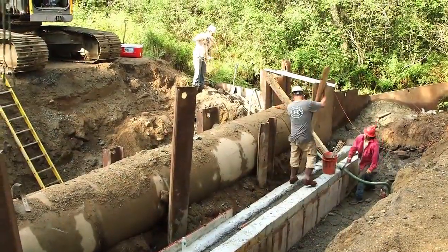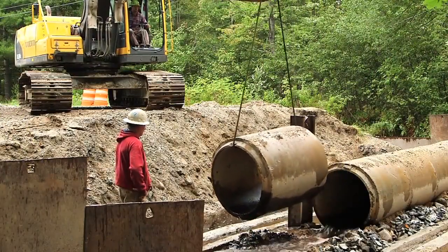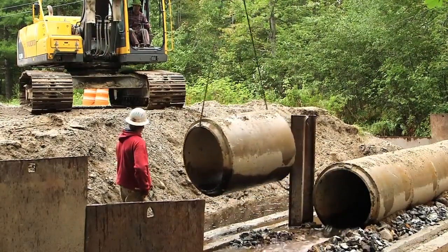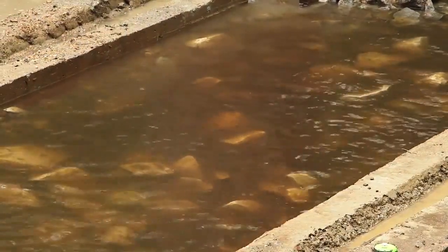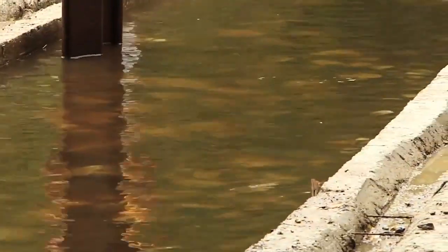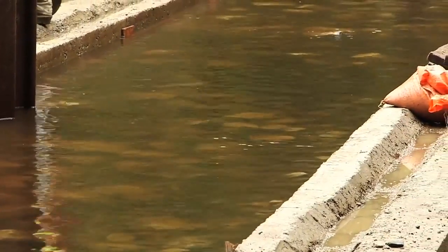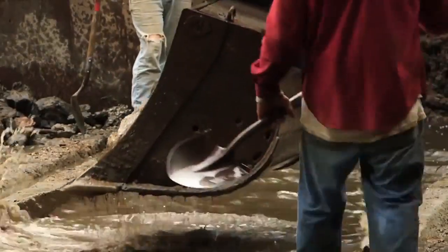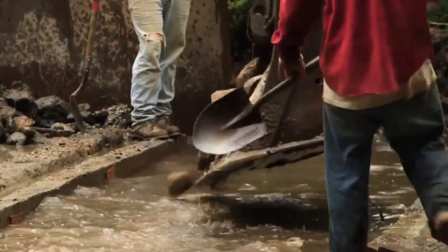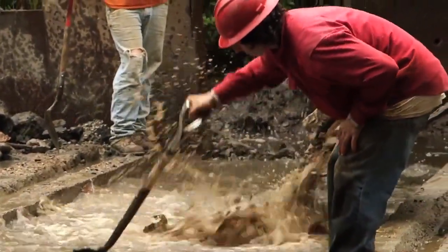Once the footings are in place, the existing pipe is removed and the channel is excavated and shaped to the design shape and elevation. During the final shaping of the stream channel, any needed riprap armoring of the inside of the footings should be done prior to placing the arch culvert on the footings. The amount of riprap reinforcement against the footings should be limited to only the amount needed for stabilization in order to minimize encroaching on the stream channel bottom.